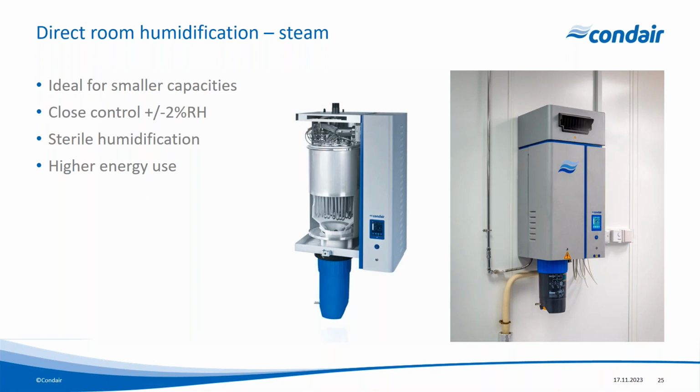Now these are isothermal humidifiers. So the previous ones that are spraying water into the air are adiabatic, whereas this is an isothermal. An isothermal meaning that there is no change in temperature, because all of the energy that's used in these is not drawing it from the air around it. It's taken from heating elements that we immerse in water, and we use electricity to heat those heating elements and produce steam at atmospheric pressure.